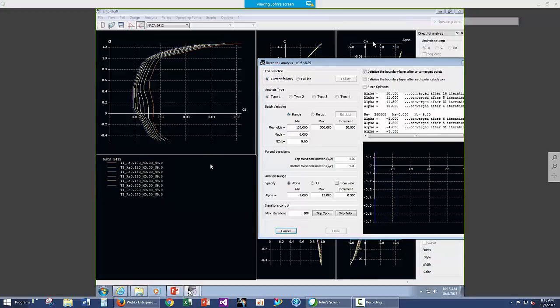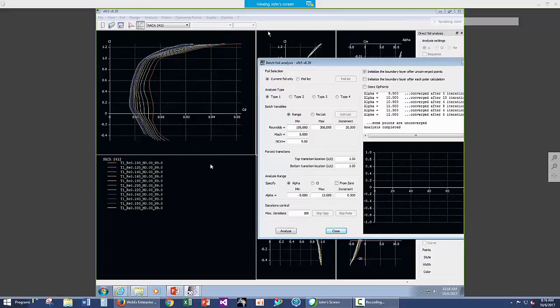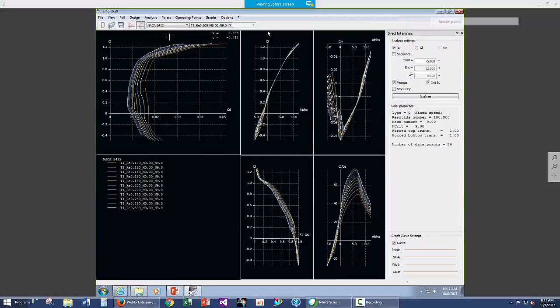This is a standard NACA 2412, a very common model airplane airfoil, 2412, 2415. So what we see then is we have drag polars, lift, drag. We see that low Reynolds numbers, 100,000, has more drag, getting to be close to twice the drag that we have at 300,000. Shape of this is pretty good.